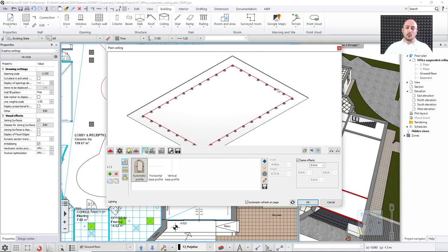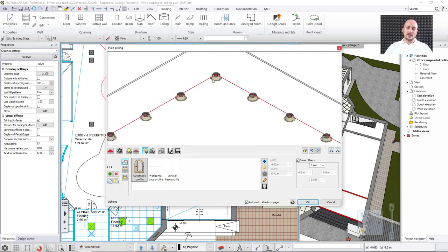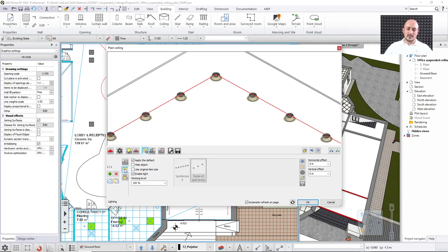And well, I have one issue with this. Just as in the case of the grid ceiling, those are attached to the bottom of this plane, which is not nice. I would like to make them synced into the ceiling. For that, I need to go to the settings of this distribution page, and here I have a horizontal and a vertical offset. I need the vertical offset, and for a fact I remember that this was 0.04 perhaps. I'm working in meters now, so it should be 0.04.